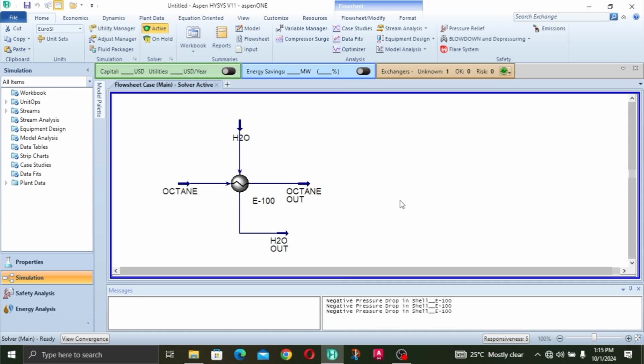Remember from our sensible heat equation, the 3 parameters affecting our thermal energy transfer: the m, c, and change in theta, the change in temperature, and that's what we just did inside our heat exchanger. We optimized to get the highest value we could get for our change in temperature. As for the specific heat capacity, that's something a little too complex to deal with. So we will also be dealing with the mass flow rate to see what we can get from it.